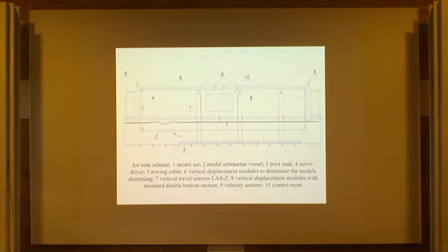Determination of flexural strength of the model was performed experimentally by testing beams, and for this purpose the model ice cover was prepared by building up ice of the required thickness, 3 mm. The average value of the flexural strength for natural ice was 0.7 megapascal. The thickness of the modeling ice cover after conversion to the natural one was 2 meters.